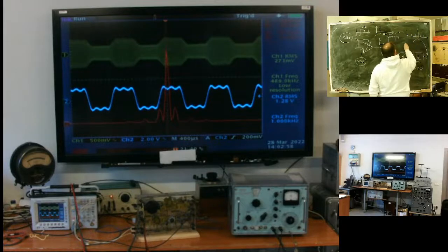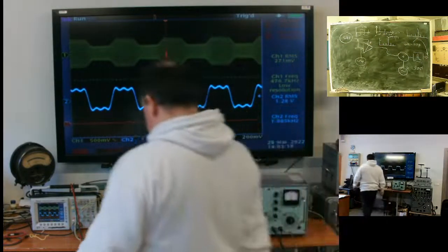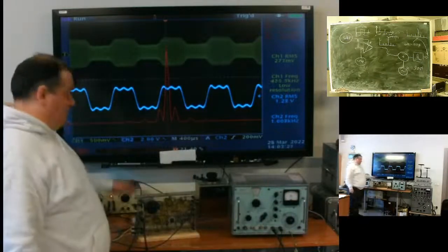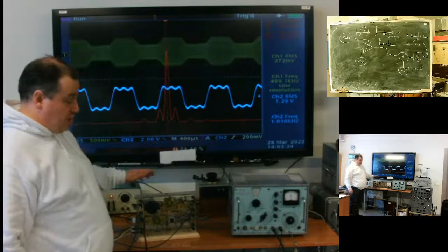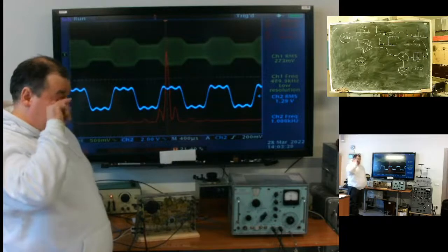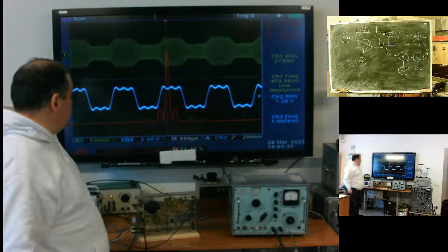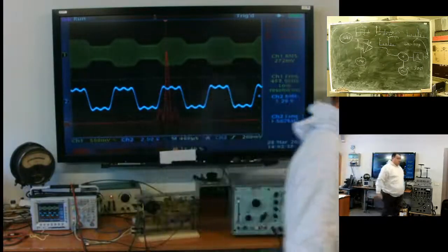In our case, omega 0 minus omega heterodyne minus omega 0. It's our case. Combining the signal spectrum with an additional generator called heterodyne and then cutting off the sum or difference at some frequency, you can transfer the signal spectrum to any frequency you need.